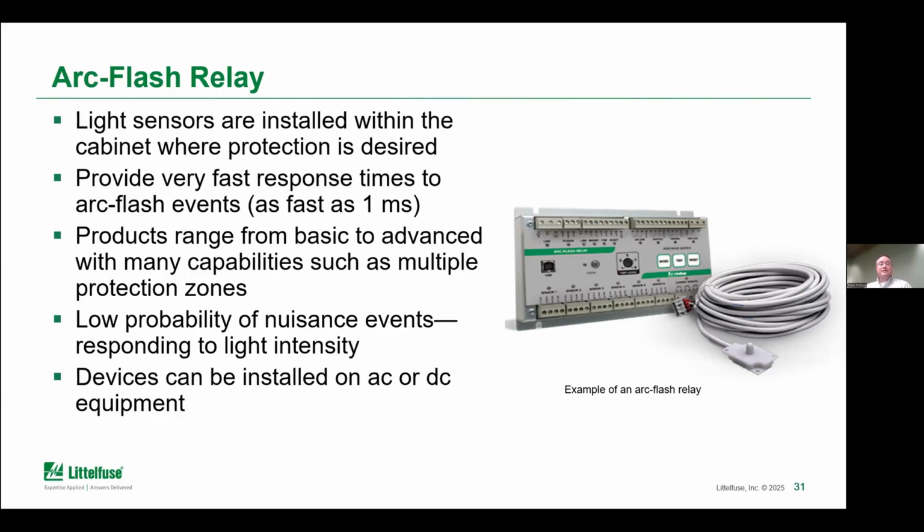So then you would need to see the light plus elevated current, above a certain level before you would proceed with the arc event. Now, one thing to keep in mind, if that's something that is done, you have to be a little bit cautious where you set that current minimum level, because you don't want to set that too high. Otherwise, you end up in a situation where you could have a very resistive arc at low current levels, but the relay is not responding.